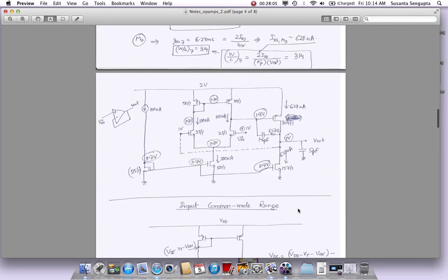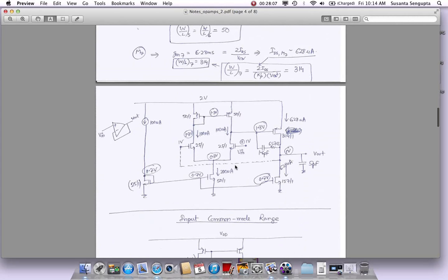So as we have done this, now we have come to this point where I think our first cut design is ready. So let's say we have a 100 microampere bias current. This will be 25 to 1. And I'm just assuming 1 micron channel length. Again, what is the channel length? You have to choose it based on the technology. So this is 25:1, which carries 100 microampere.